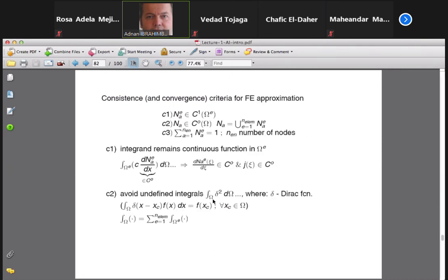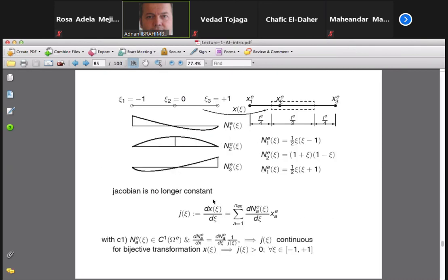But basically, if we have now higher order approximation, we still have this unified domain that goes from -1 to +1, but Jacobian becomes non-constant if the mesh is not perfectly respected. So basically, that is something to worry about. As I said, initially people tried to compute high order approximation with these elements, but it turned out that they have so much sensitivity and they are good to obtain some special solutions. But if you have a very general problem, nowadays people really prefer much lower order approximation, which is much more robust, and they can avoid all these difficulties.